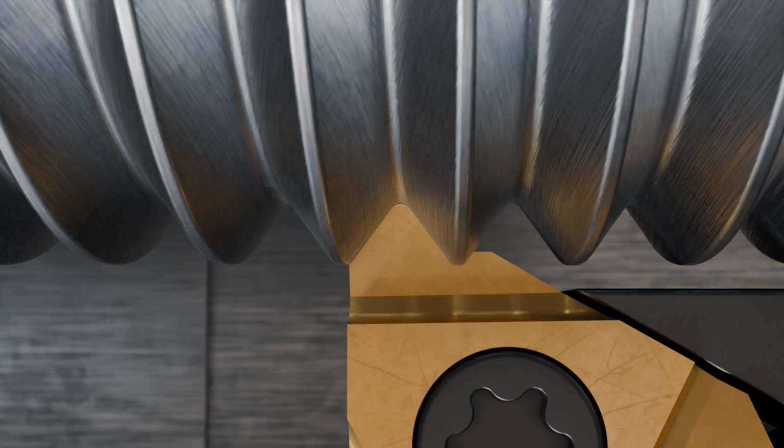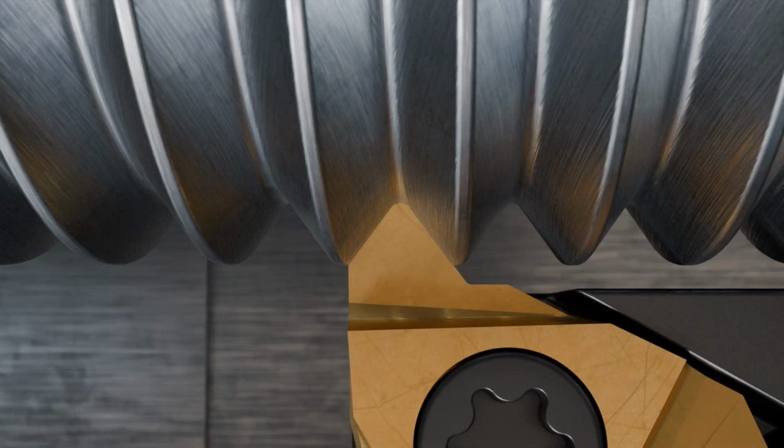To reduce the number of different inserts, there are also inserts with a so-called partial profile. These cut only the thread root and the thread flanks, but not the thread crests. This way, threads with different pitches can be produced using just one insert. The prerequisite is, of course, that the thread profile cross-section is the same in all cases. The starting diameter of the workpiece must exactly match the outer diameter of the thread without any allowance. Usually, however, a burr forms on the thread crests that must be removed afterwards.